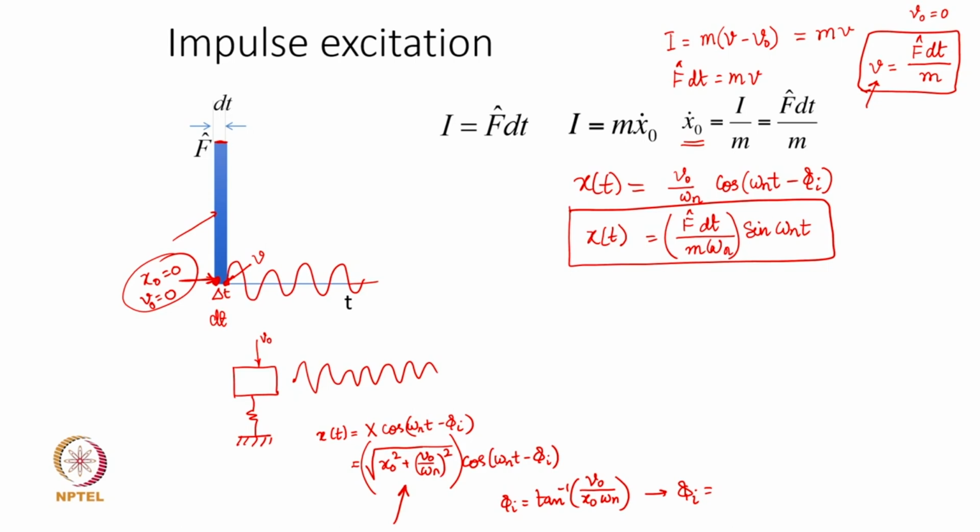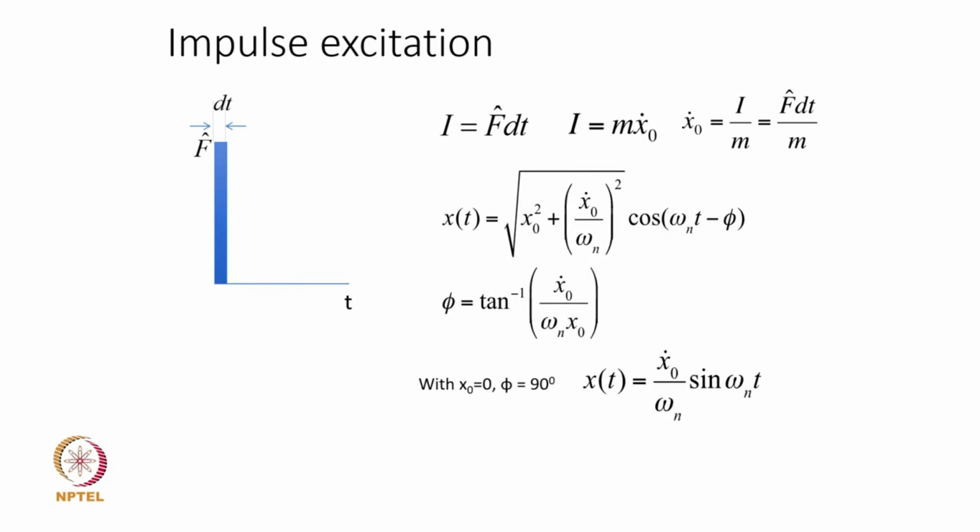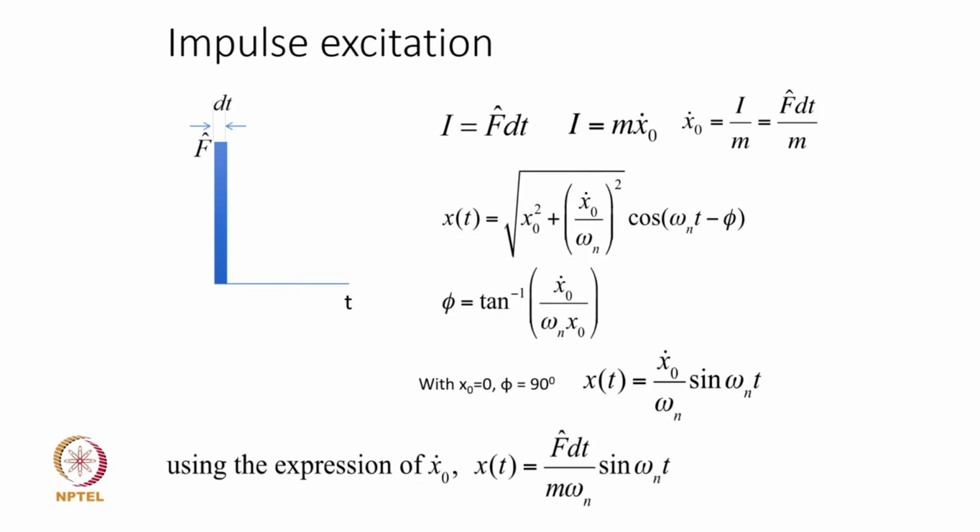And it is important that what we have assumed is that we are going to use these impulses one after the other, of different amplitude f, to represent an arbitrary excitation function. This is what we have obtained, and this is the exact expression that we have already derived. So, that basically is the response expression x(t) if the system is subjected to a solitary impulse.